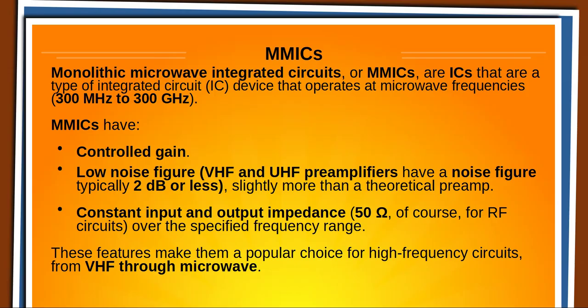They have a controlled gain. In other words, it's pretty much fixed. It's just a little block, amplifier block. Very low noise figure, 2 dB. In other words, it raises the noise floor 2 dB, which is not much. In dB, it's actually what? 40%? No, guess I said everything there. Normally, you're going to see it in VHF microwave type things.